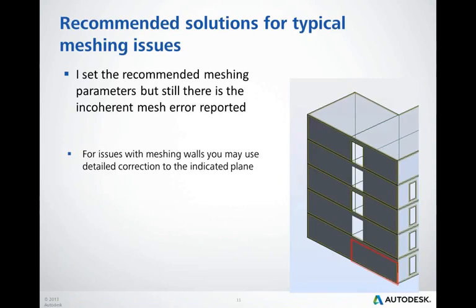Let me show this option on an example which has incorrectly defined wall opening. In addition, I will use this model to show what influence on meshing a wrong snapping during panel's contour definition has got, and demonstrate the way to correct such situation by moving the characteristic points of a panel's contour to the right location.